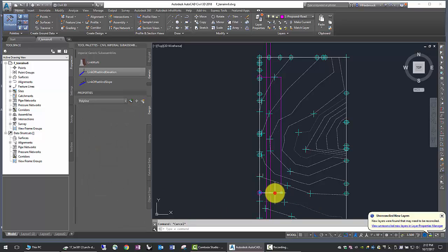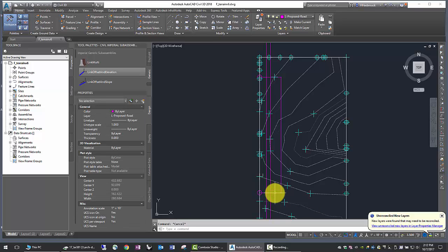Now I can repeat my polyline exercise, p-edit. Yep, turn it into one. Yep, join it to its neighbors. And success, hopefully. See, 2 segments added, good. So we're going to use this as the base information for my alignment.